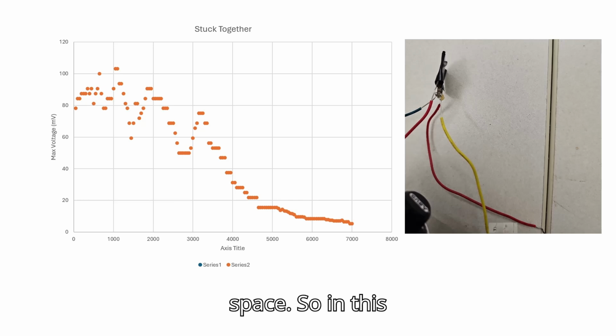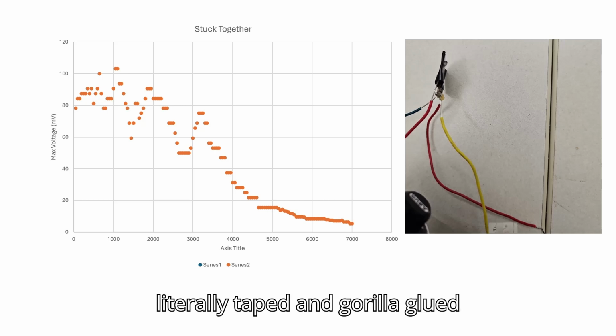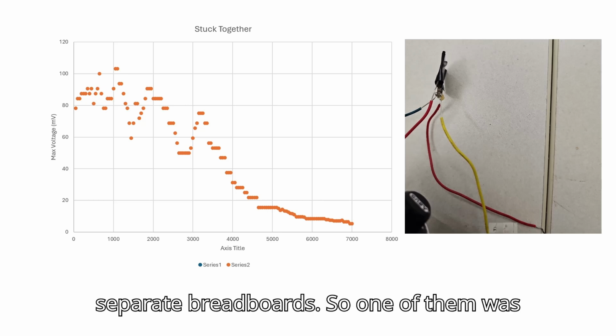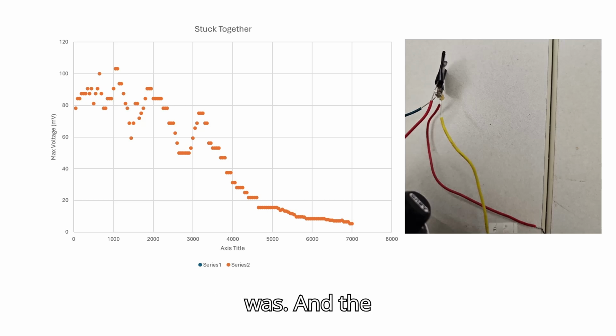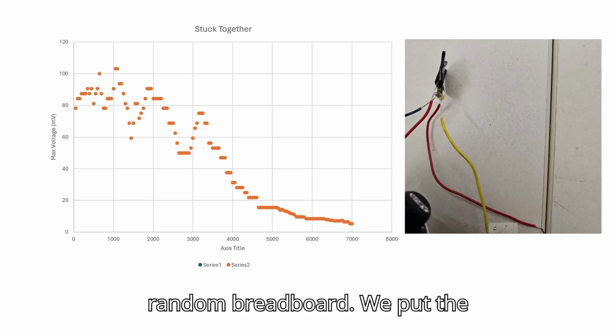In this slide, the two piezos are stuck together. They're quite literally taped and Gorilla Glued together, and they were attached to separate breadboards. One of them was attached to the whole op-amp circuit to get the 12, 13, 14 volts, whatever it was. And the other side was attached to just a random breadboard. We put the oscilloscope across it.